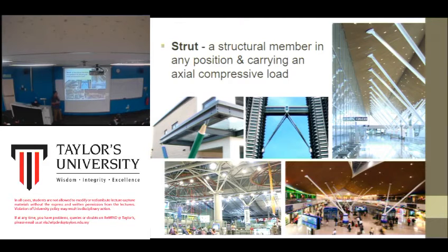So not necessarily do you need to have a straight column, especially when it comes to the entrance. To enhance the appearance of the entrance, the front facade, you can try something like this, right? So it doesn't have to be straight, but you can't have it only slanted in one direction like this. Normally, if you want to do something like this, you need to have one column going straight up to support the load, and additional struts supporting the other side. And you can see from this image, again, basically it's symmetrical. This one is supporting the roof and the ceiling. You can see that you have two sides, right?